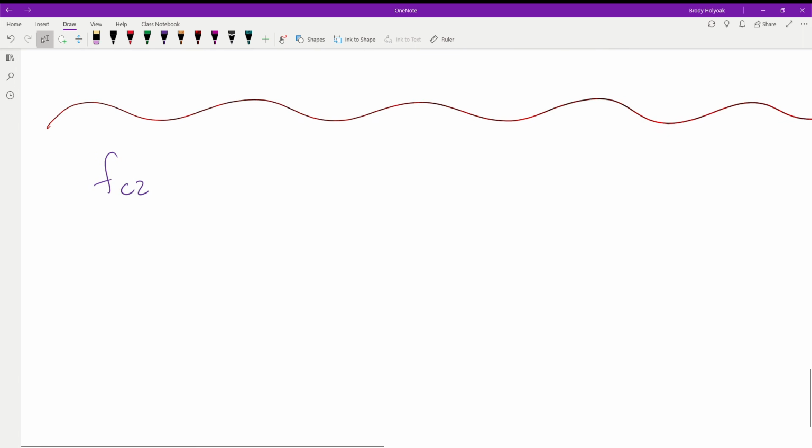So now the first step is we need to find our R Thevenin across the capacitor 2. So the first thing that we have is we're going to short the power supplies. So we're going to short our generator, short our VDC, and we end up with, let me draw this in the same orientation. So this is our VGen right here that's been shorted to ground.